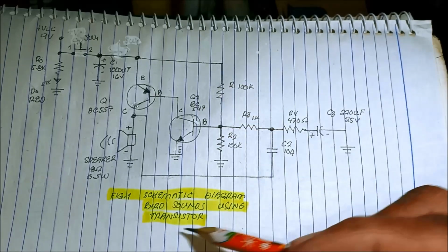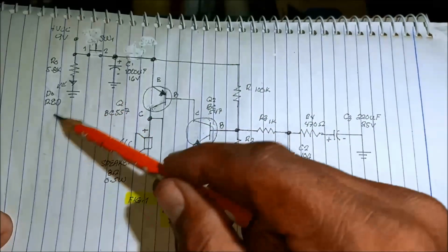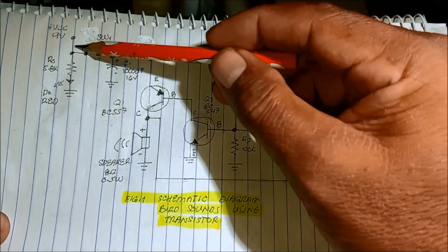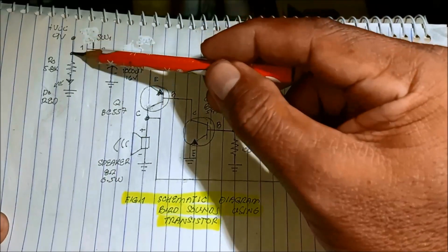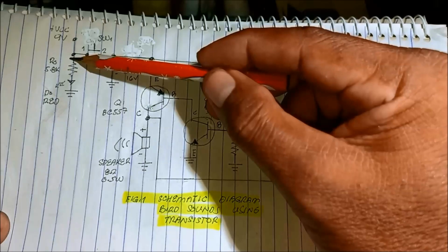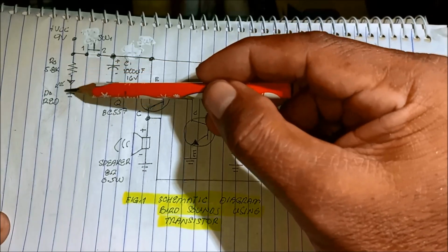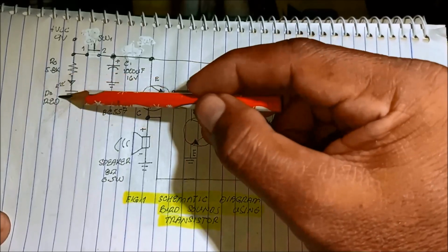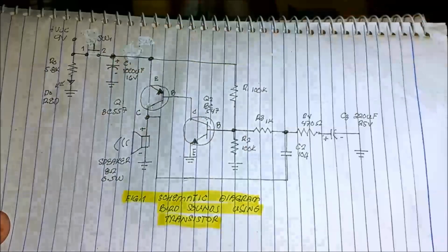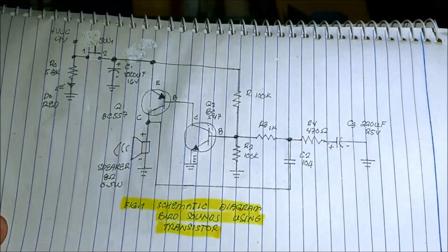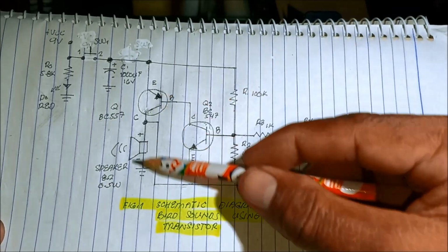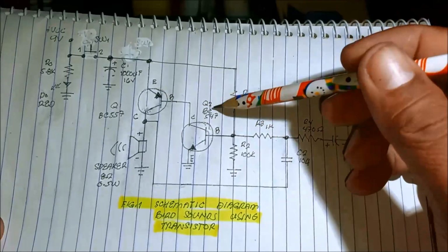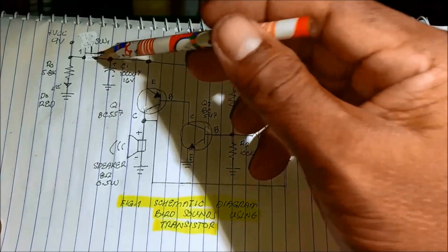Initial state of the circuit, only the power LED turns on because there is a current that flows from the supply 9 volts to the current limiting resistor, then to the LED, turning this LED on. So we have this power indicator LED, it is on, but this whole circuit is off because the switch is open.